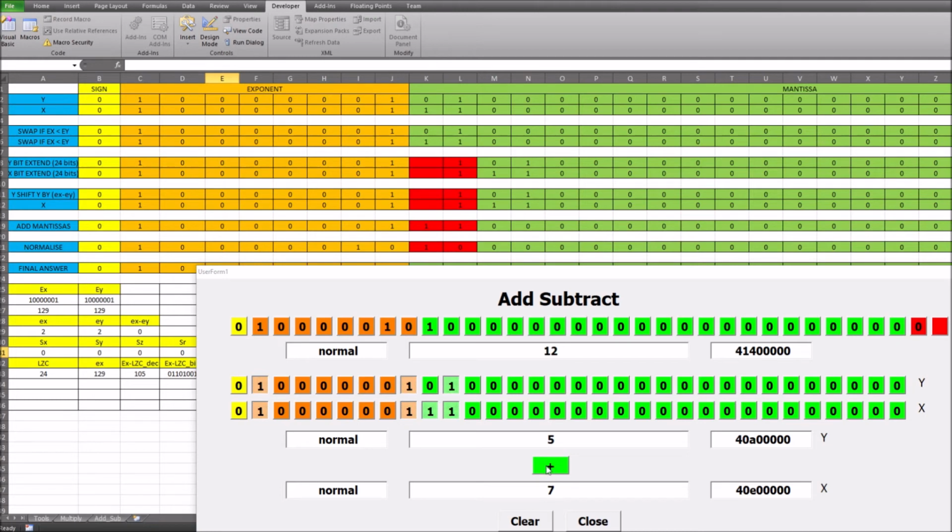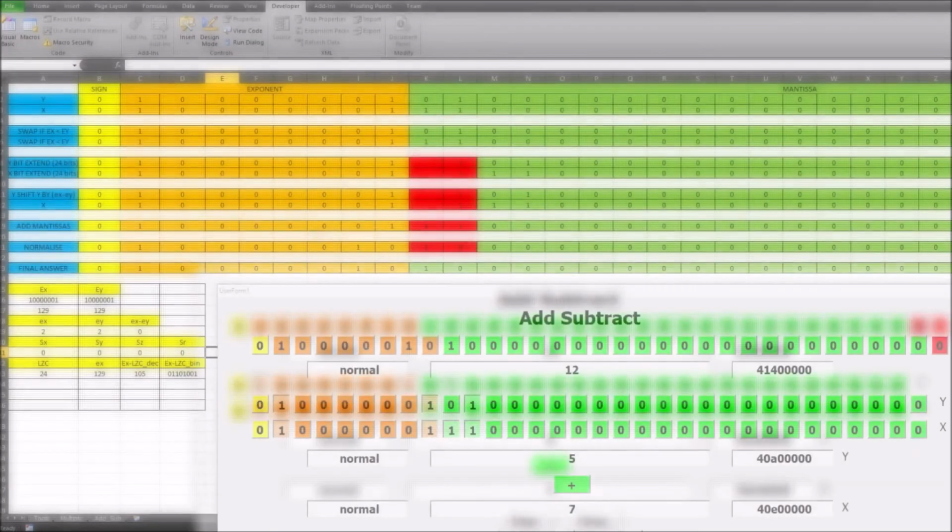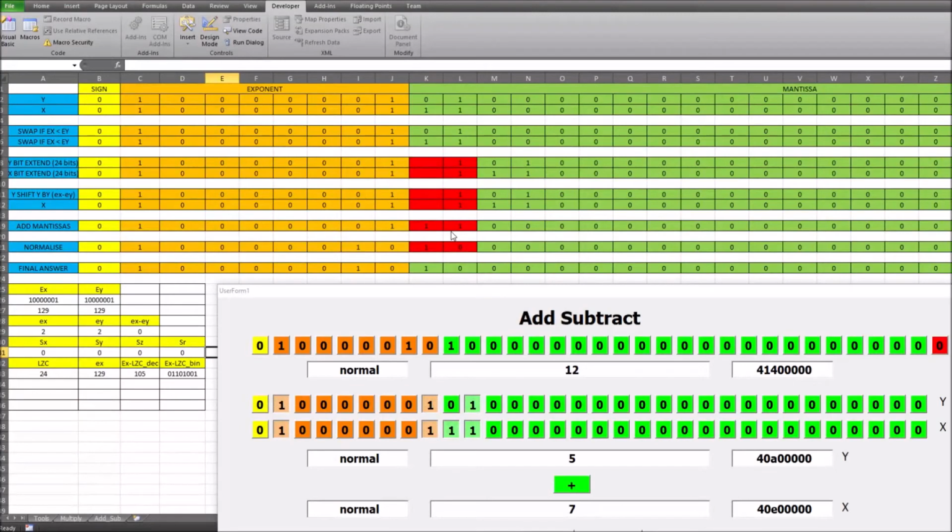So we've had to add 1 on to the exponent in order to get it into the correct exponent bin, and that's what this carry out does. It carries out of here and it ripples up through and adds 1 on to the value for the final exponent. So finally we're going to have to normalise the result and get rid of the hidden bit.